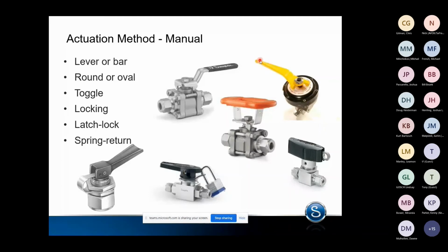If you operated this valve to fill a vessel, a bucket, or a cylinder for sampling, and hypothetically the technician, when he's done gathering that sample, walks away and leaves the valve open, you don't dump the rest of the system media out. The spring assist allows that to close itself, to go back to a normally closed orientation.